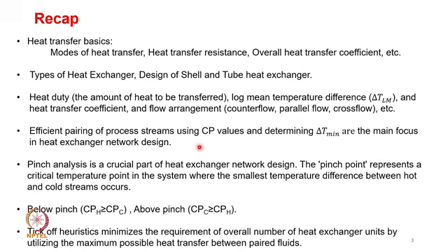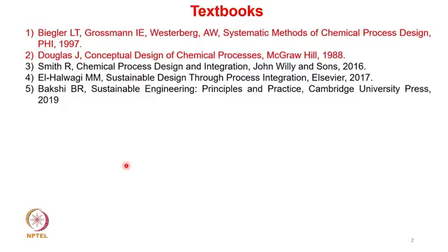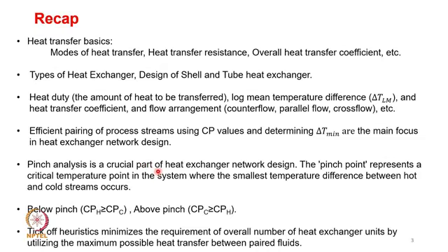Further to that, we looked at pinch analysis, a crucial part of heat exchanger network design. The pinch point represents a critical temperature point in the system where the smallest temperature difference between hot and cold streams occurs. So controlling the pinch point is an essential thing in the design of heat exchangers.